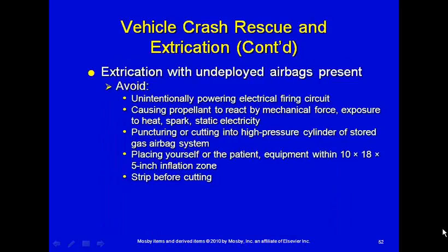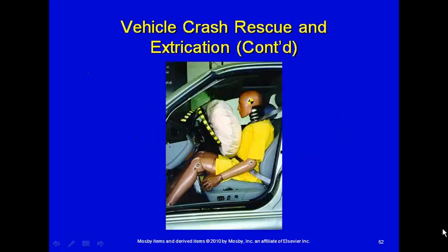As far as extrication, an undeployed airbag is present. Avoid unintentionally powering the electrical firing circuit. It may cause the propellant to react by mechanical force and exposure to heat, spark, and static electricity. Don't puncture or cut into high-pressure cylinders of stored gas in the airbag system. Don't put yourself between the patient and the airbag. Strip the cord before cutting.